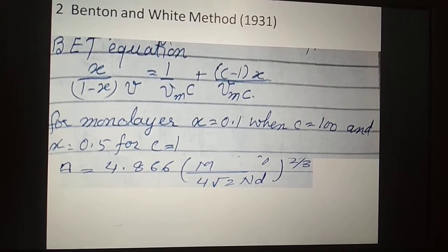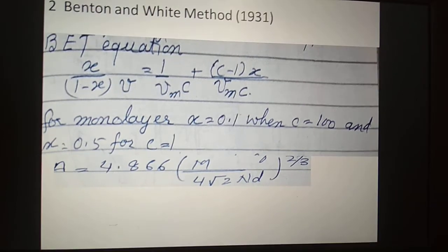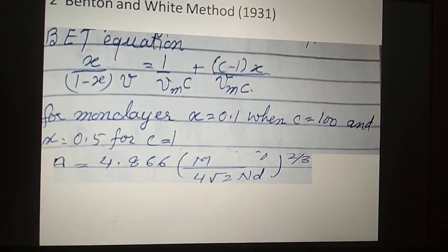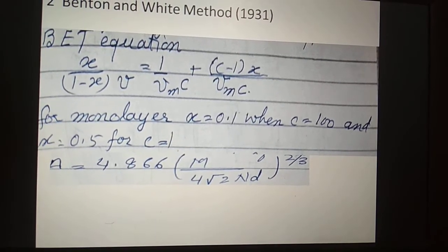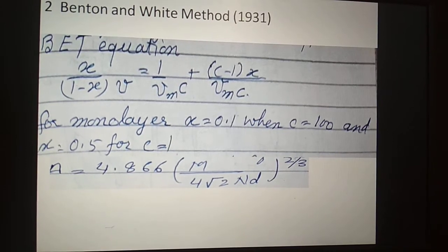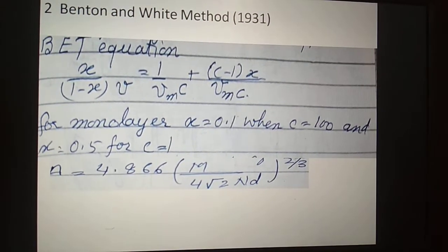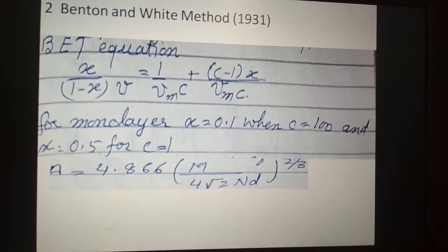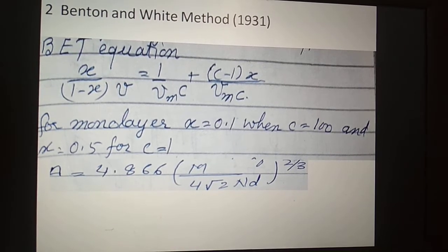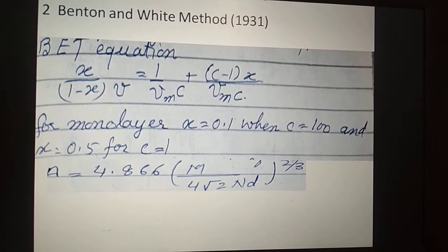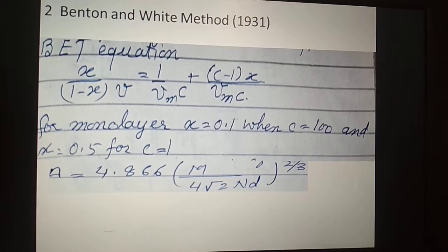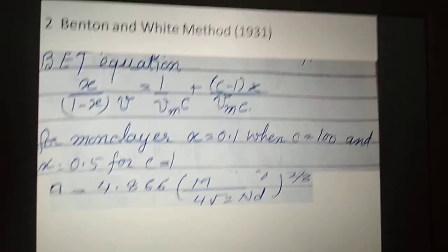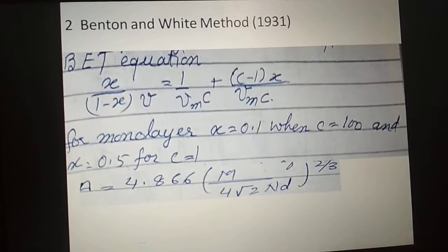For measurement of surface area, nitrogen is commonly used as the adsorbent, but the areas obtained by the use of adsorbents other than nitrogen differ in many cases due to the larger molecules being screened out of some of the pores of the adsorbent or due to irregularities in packing of various molecules on the surface.